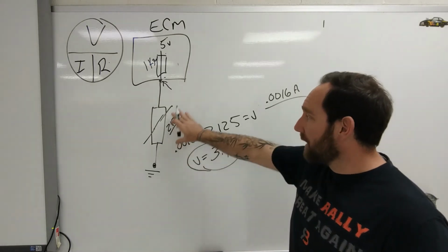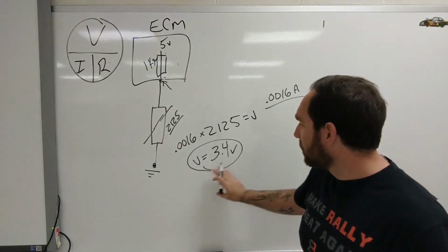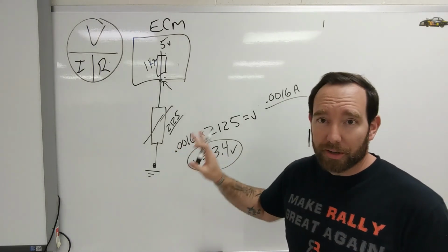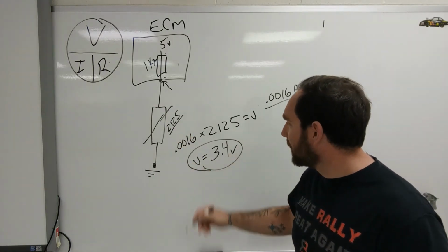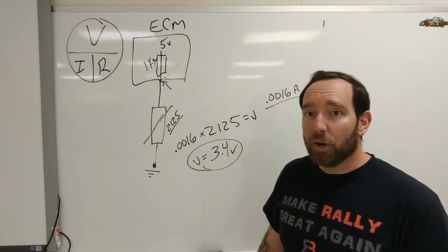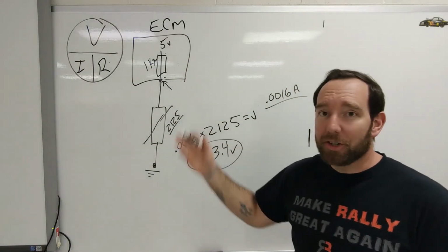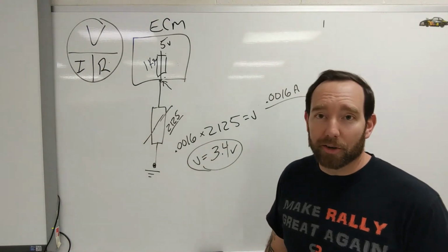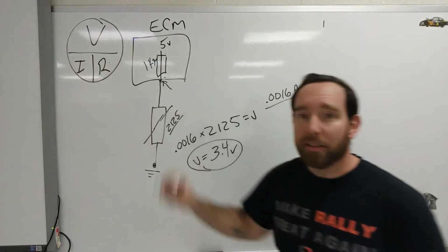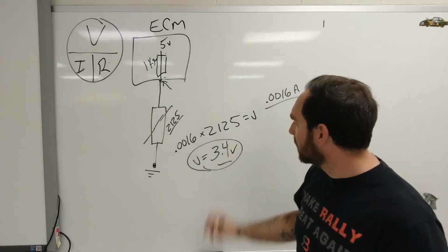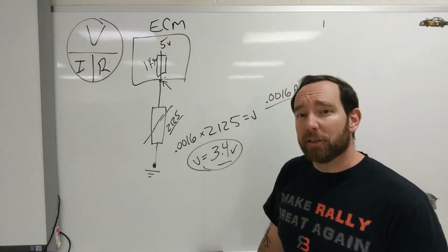And then because of the way this system works with this PTC thermistor, this will increase as temperature increases, all right? So there's your answer. Pretty basic. We used total circuit resistance, adding this to this, and then we just used Ohm's law twice to figure out what we needed. First, total current, so we solved for I first, then we solved for V, okay? Once we knew that. That's all there is to it, okay? It's a very basic circuit.